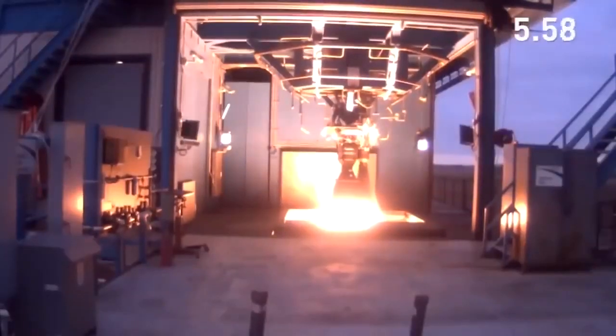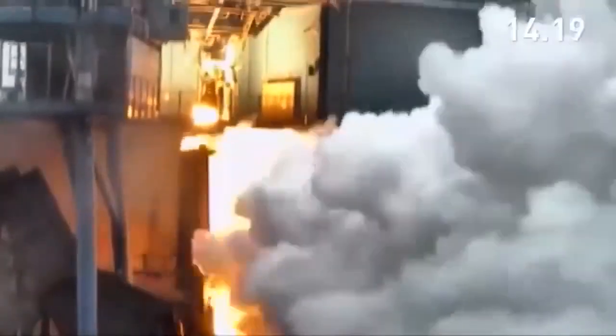With a gas generator, all the exhaust gases that were used to spin the turbine are simply dumped overboard, or perhaps maybe used to cool portions of the nozzle, but the gases are not added into the main combustion chamber. That's why this is called open cycle. The exhaust gas is used and then it's expelled to the open air or space. It's not used in any part of the main combustion process.